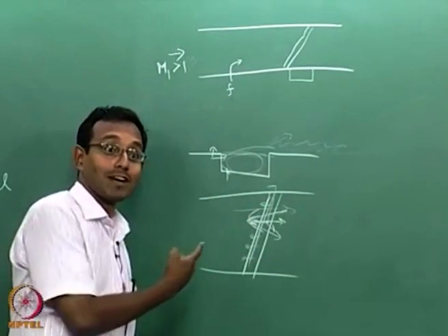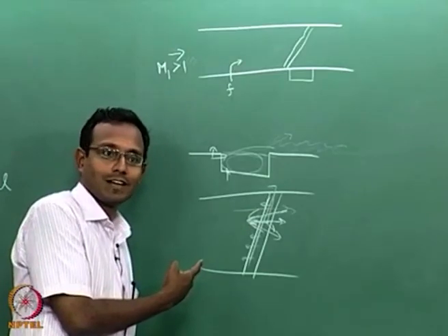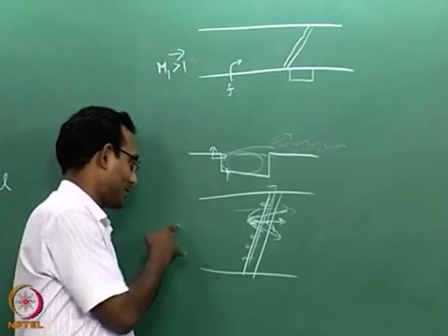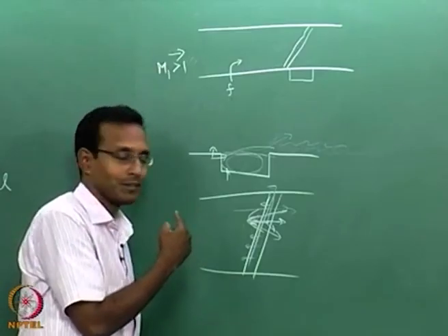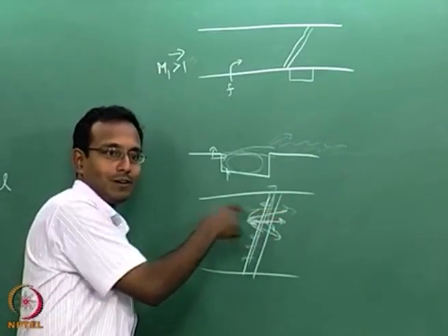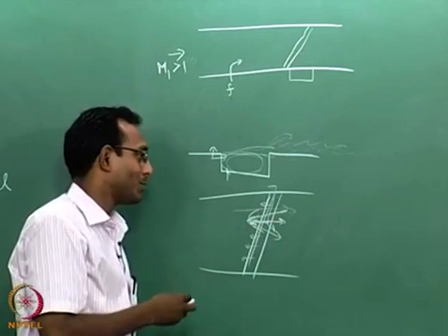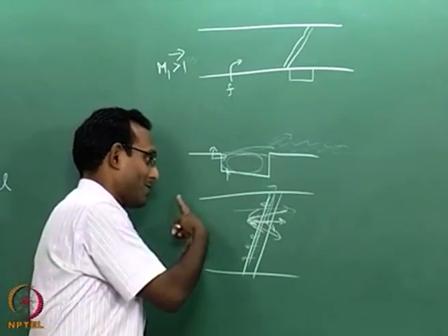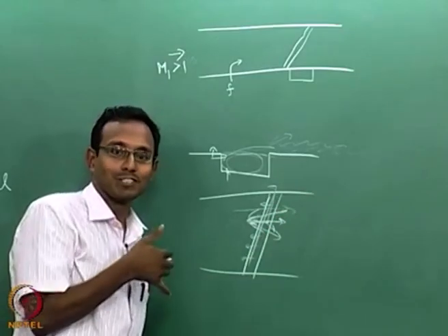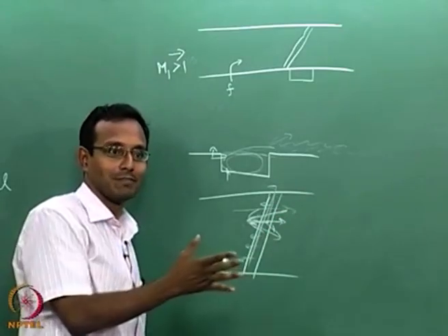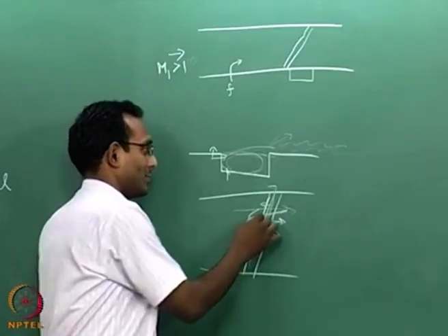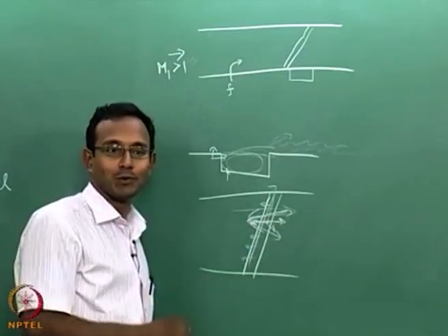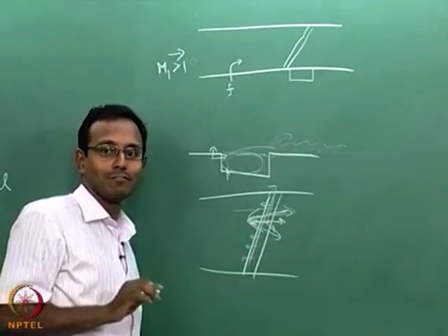Now I have to think about mass addition. I just added mass and the fuel evaporated because the incoming temperature is already hot enough for me. Once it evaporated, that is also going to occupy space. So already if I have a constant area duct, I am having more congestion, more people running in the same area. I am getting towards choking already just by adding fuel.